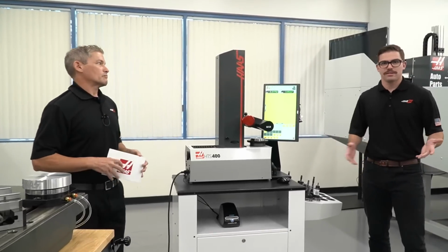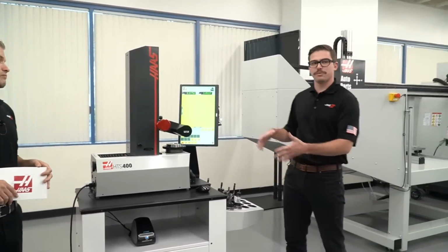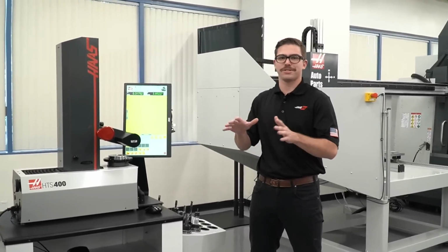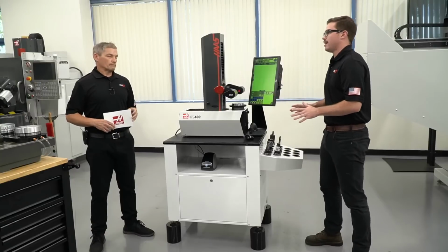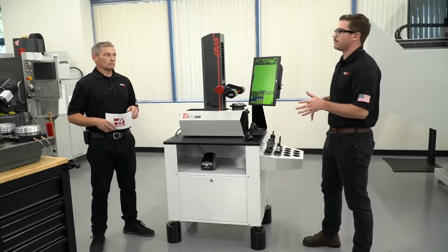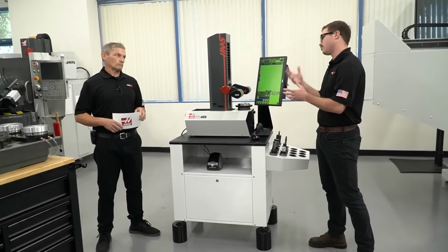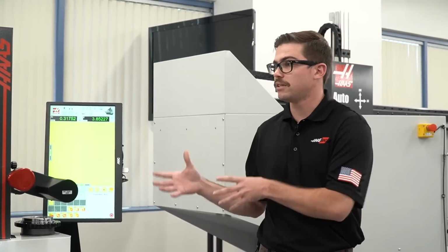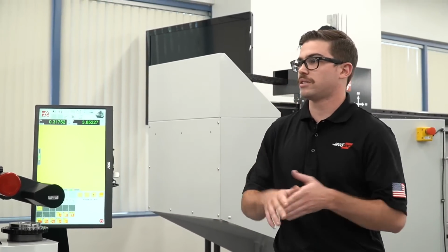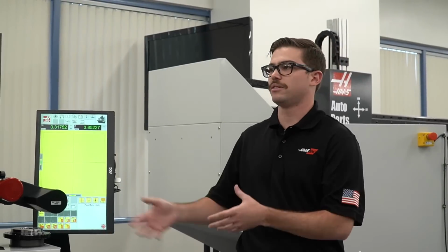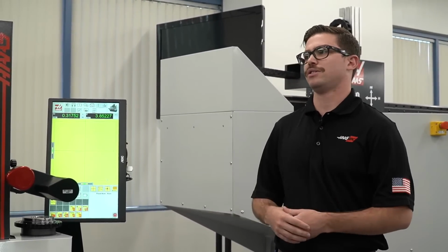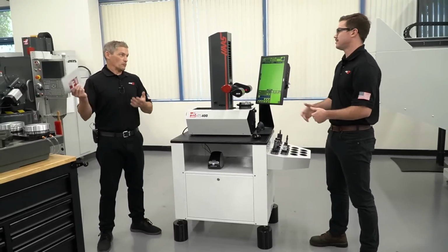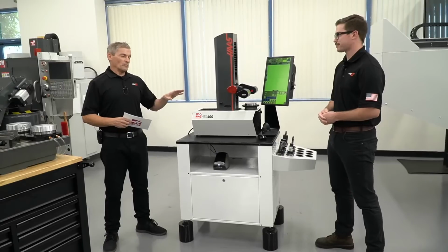Yeah, so for those of you who haven't encountered a tool presetter before, essentially what a presetter does is it takes the operation of touching off and setting your tool offsets, which has to be done primarily inside of your machine, and makes it something that can be done offline. So it allows you to continue making parts and continue to run your spindle, while still being able to touch off your tools and set up tools for either replacing the tools in your current job or setting up a brand new job. That allows you to make more money at the end of the day. You're running your spindle longer and more often per day, so you're making more money. Exactly. Cool. So something that's going to pay off for sure.